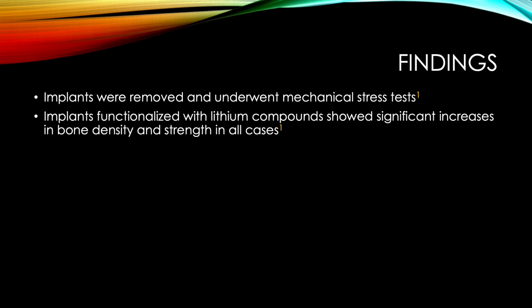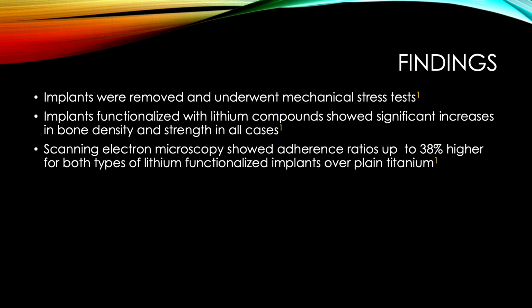The implants functionalized with lithium compounds, that's lithium carbonate or lithium phosphate, showed significant increases in bone density and strength in all cases. In addition, scanning electron microscopy showed adherence ratios up to 38% higher for both types of lithium functionalized implants over the plain titanium implant.